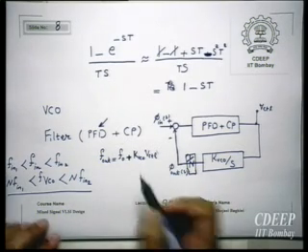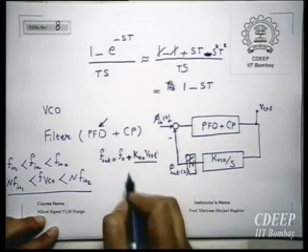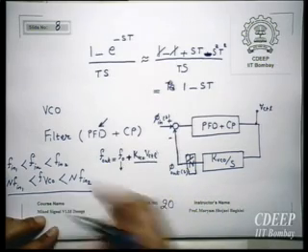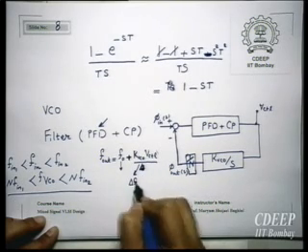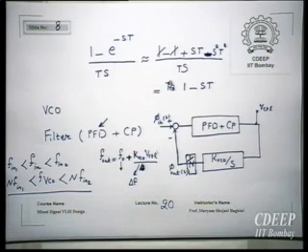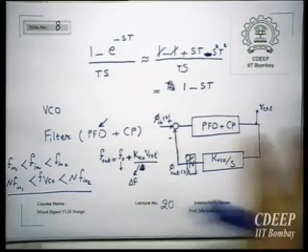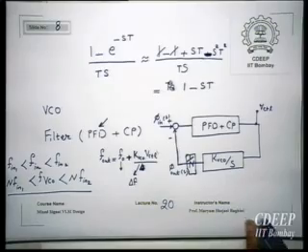So this, in fact, F0 is the average of these two, therefore this will give me delta F, which will be the bandwidth I have around this center frequency, (Fin1 plus Fin2) upon 2. So this is one of the things that I will look at, and then accordingly I will design my VCO. But when it comes to the loop stability, loop bandwidth and jitter performance, then I will look at the charge pump and phase frequency detector.